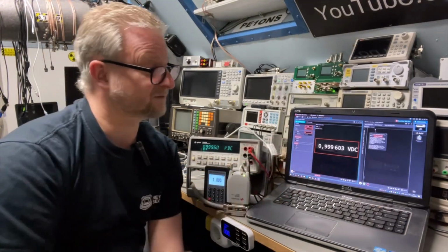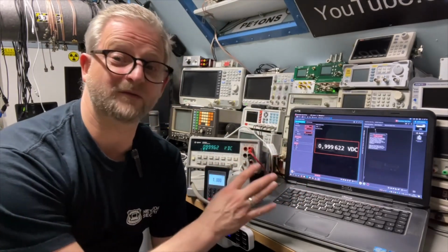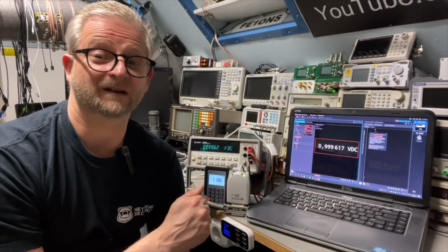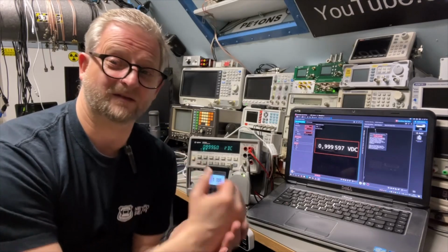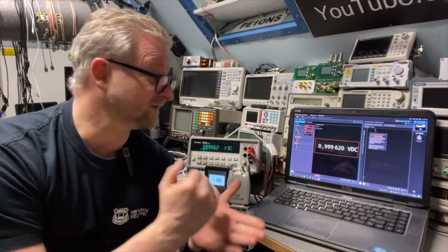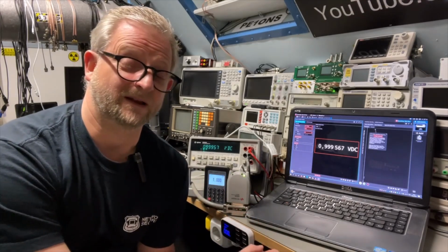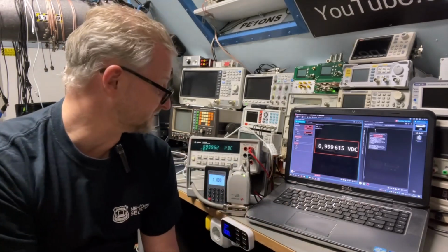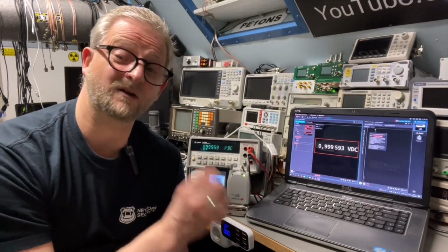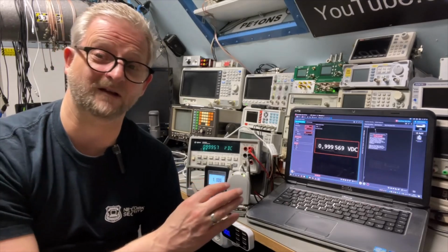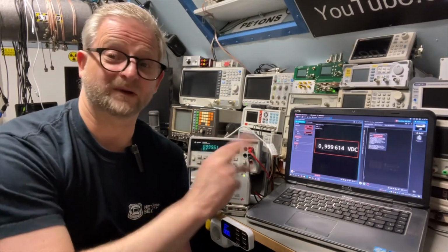I use this from HP to install the Keysight software. I did first install the National Instruments software because that VISA driver, I have read many articles about it, that VISA driver from National Instruments is the most compatible. And so if you install that first and after that you install the Keysight software, the Keysight software will recognize, oh, you already have a VISA driver installed, let me be at least a secondary. So you can switch then maybe later.